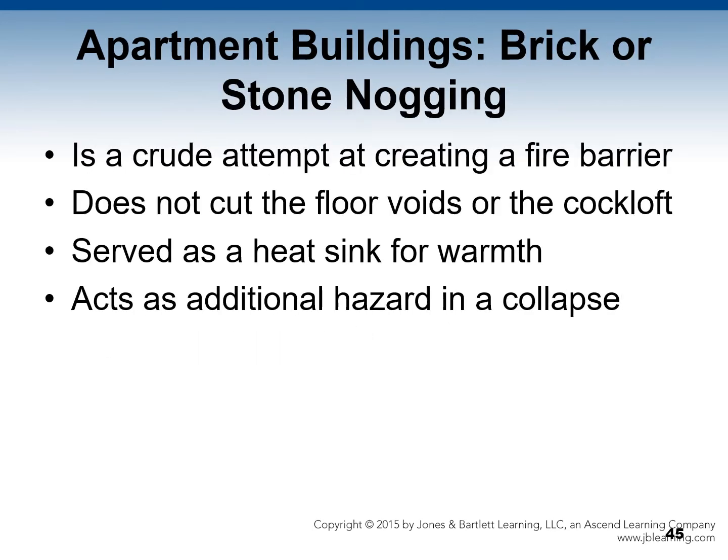Now let's talk about brick nogging. This is a crude attempt at a fire barrier, and we talked about it before. It's that brick that's put in between these stud beams. Brick nogging does not cut the floor voids or the cockloft, and brick or stone nogging can serve as a heat sink for winter warmth.